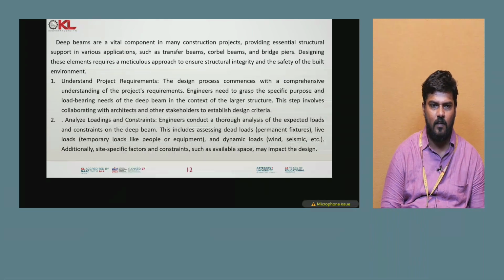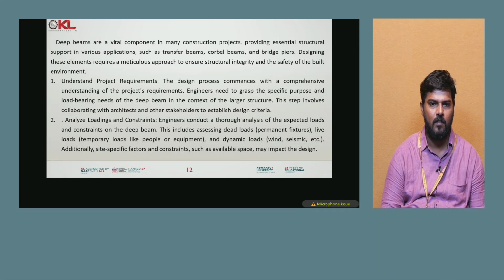The next thing is analyzing loadings and constraints. Engineers conduct a thorough analysis of the expected loads and constraints on the deep beam. This includes assessing dead loads such as permanent fixtures, live loads, that is nothing but temporary loads like people or the equipment which is kept on the deep beam, and dynamic loads such as wind loads, seismic loads, water loads, etc. Additionally, site specific factors and constraints such as available space may impact the design of the deep beam.